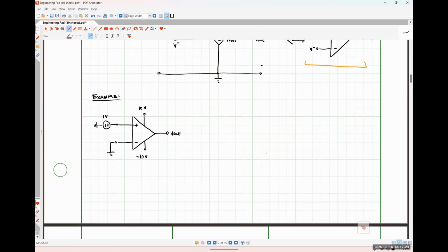And let's say that the open loop voltage gain for this amplifier is 100,000 volts per volt, okay? That is actually not particularly good for a well-designed operational amplifier. A well-designed op amp, one that's meant specifically for providing voltage gain, can have voltage gains of a couple of million pretty regularly. So 100,000 is average at best.